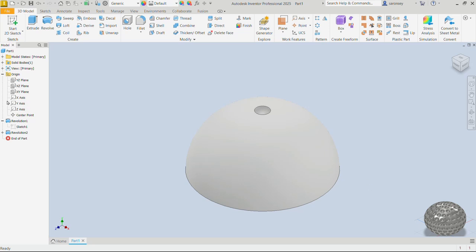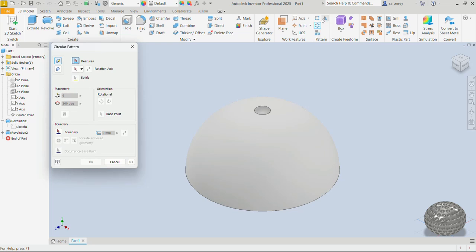So what we want to do next is to create a circular pattern. We would pick that command here. It is under the pattern group. The feature we want to create the pattern of is going to be this first dimple we created. Now the axis we want that to go around. Let me open up the origin that is opened already. And so let's see, we want to move this way. That is more like in the clockwise direction. So the axis we can go around can be the Z axis. Let's see the Z axis. There we have it here.